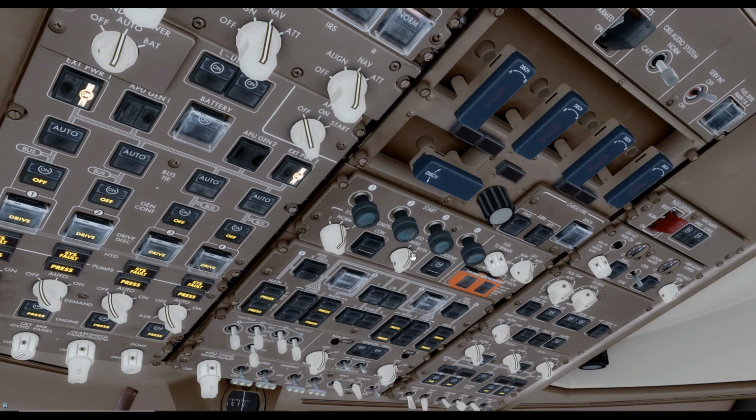The auto ignition selector should be in single, and the auto start push button we have on in preparation for engine start. All normal engine starts should be done using the auto start feature, unless of course you're flying one of the older model 400s which don't have the auto start feature.